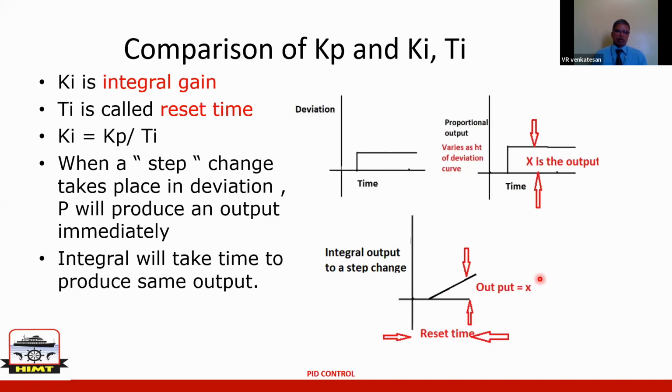So it will take more time to make corrections. Take simple examples. Many of you would have sailed on tankers. If you have a tanker with a boiler supplying steam to cargo turbines, and the cargo turbine speed is increasing or more turbines are brought into use, the water level will come down. You agree? Yes. The water level will come down, then it will come back to the normal level.